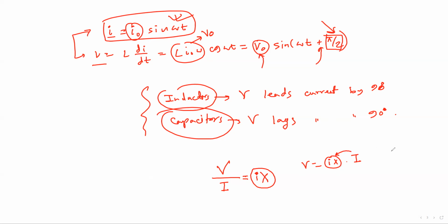And in case of a capacitor, the voltage by current relation is a 90 degree clockwise rotation, in the negative direction, right? So you have a purely imaginary negative number. Now what we do is, for inductor we write subscripts like this, and for capacitor we write subscripts like this to make more sense and distinguish between them.